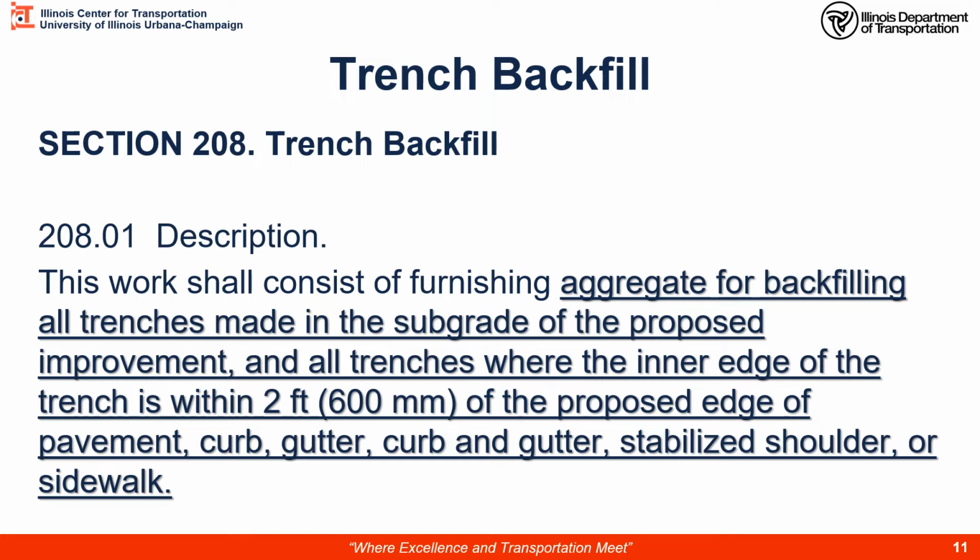Let's talk a little bit about the trench backfill material. If you're away from the roadway or a sidewalk or any other type of structure, it really doesn't matter what type of material you put back in, as long as it came out of the trench, you can most likely put it back in the trench. However, once you get around the pavement or curb and gutter or sidewalk, we want that to be a stable environment. We don't want any long-term settlement over that piece of pipe that had that backfill.